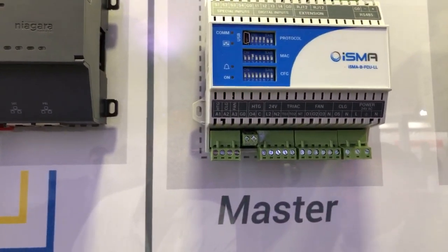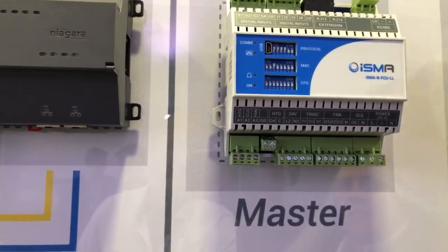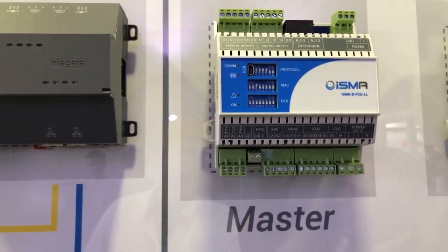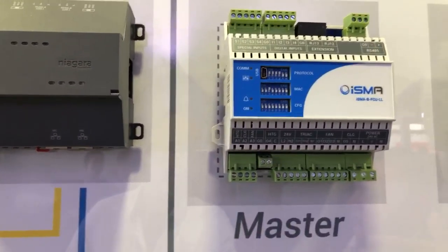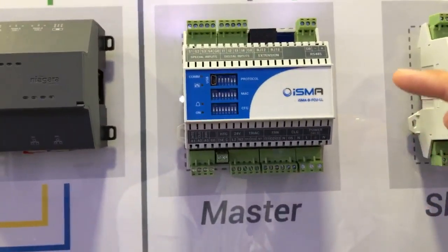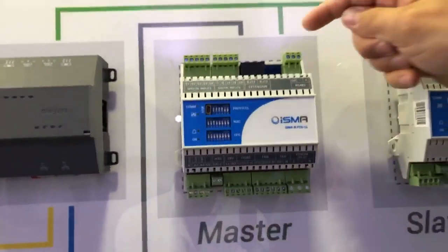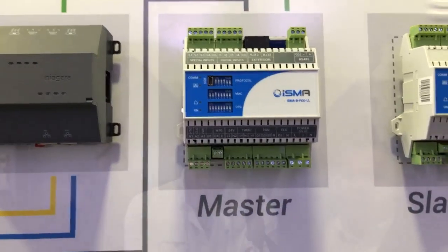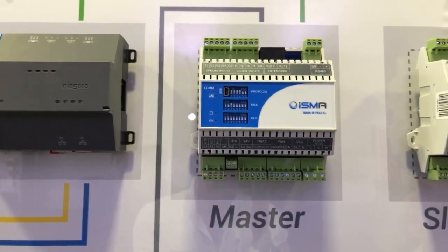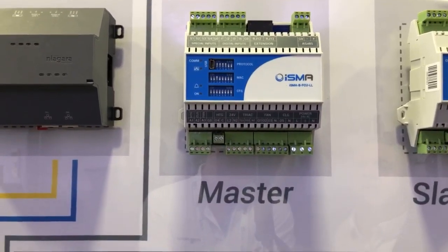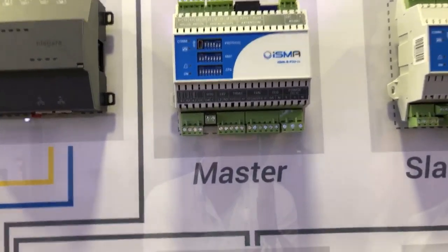But it's a fully programmable controller with 18 inputs on board. So if our application doesn't suit the solution, then you can always change the application and reload it through USB or even through RS-485. We've got special tools so you can load it. Best of both worlds: it's configurable with dip switches, but if you want to change the program, you can completely reprogram it. It's Sedona driven.